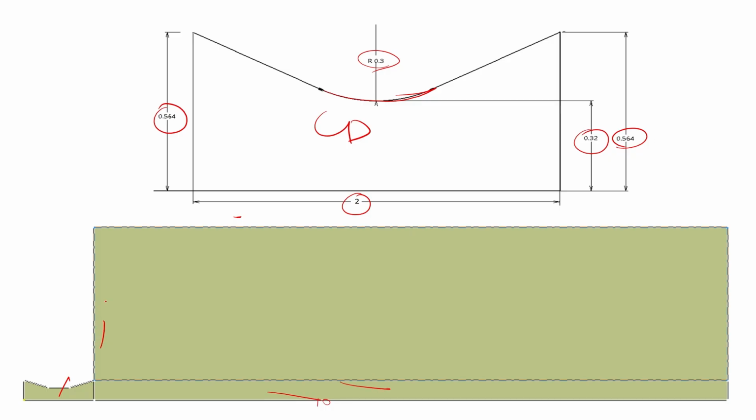Then vertically I have taken around 5 times the nozzle length. Okay, so horizontally I have taken more than 10 times the CD nozzle length, vertically 5 times the length. Like that I have defined the flow domain. Then in CATIA, using the fill option, I created the surface. Then using the split option, I divided this into 3 blocks. Okay, with the blocking I have finished.